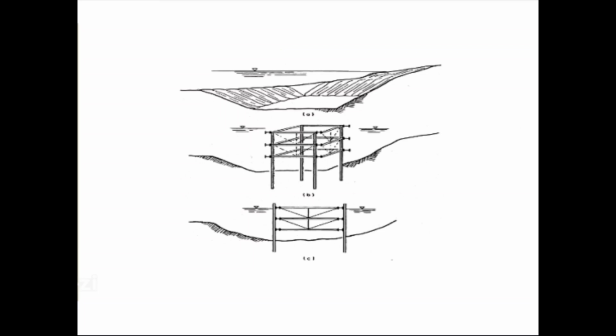Temporarily erect the bracing frame on the support piles. Figure C, set steel sheet piles starting at all four corners and meeting at the center of each side. Drive sheet piles to grade. Block between the bracing frame and sheets, and provide ties for sheet piles at the top as necessary.